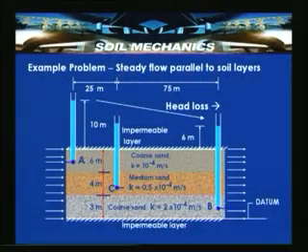So, we have discussed stratified soils and how the equivalent permeability can be computed, and we also said that generally for stratified soils Kh is not equivalent to Kv, but it is observed that Kh is greater than Kv. The reasons we have explained through the geostatic stress principles. Let us now look into an example where the flow is occurring in the horizontal direction.